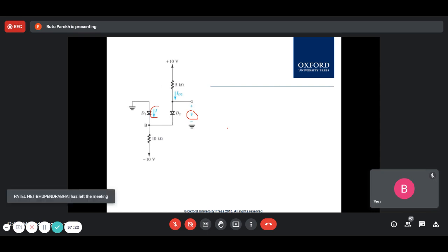Because electronics is all about I and V. And if you can find out the direction of the current, if your answer is positive, that means your assumption is correct. Positive means whatever direction or polarity you assumed is correct. And if your current comes negative, that means the current should be flowing this way. Hence, the diode must be connected the other way, right? Because if you are getting a negative current, whatever the connections are now, you have to flip it. So the diode connection will be the other way. The supposition you made was wrong, and you resuppose with the options that are left.